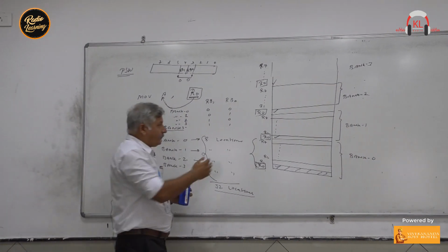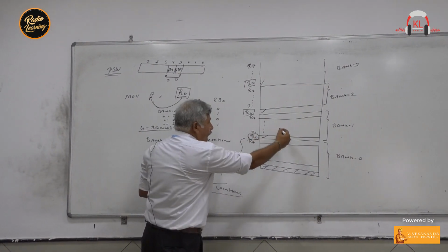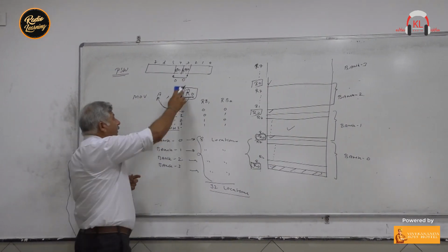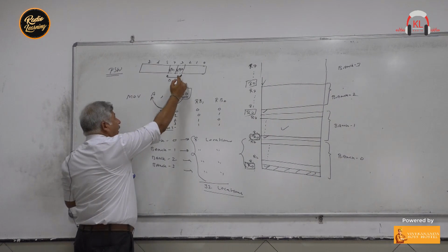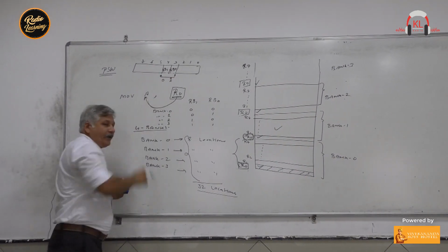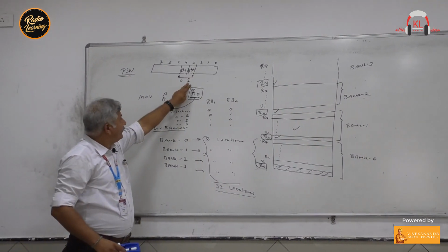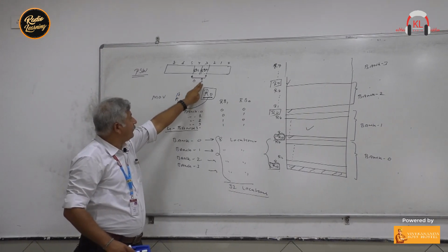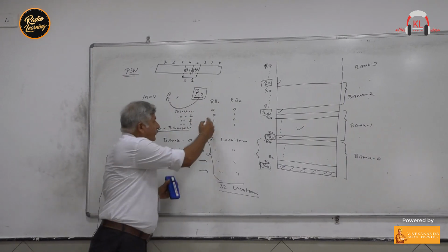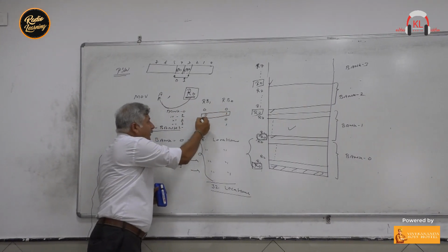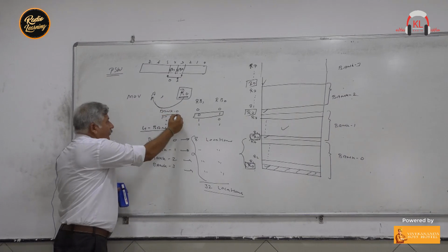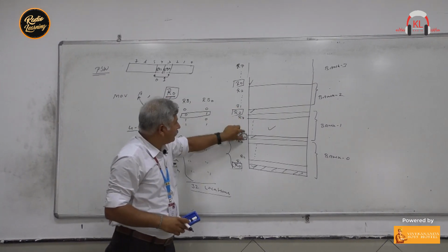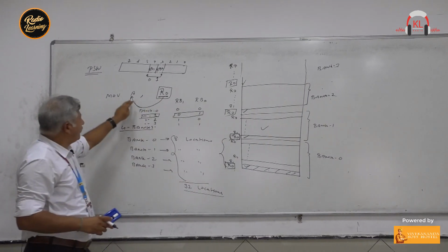And if we want the content from R0 of bank number 1 to be transferred to the A register, then we have to make RB0 1. RB1 is 0, RB0 is 1. In this case, bank number 1 will be selected, so the value from R0 of bank 1 will be transferred to A.